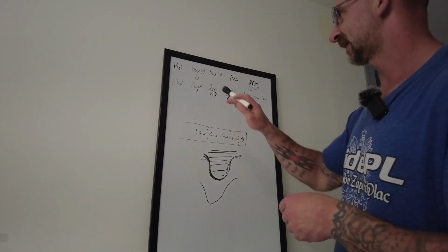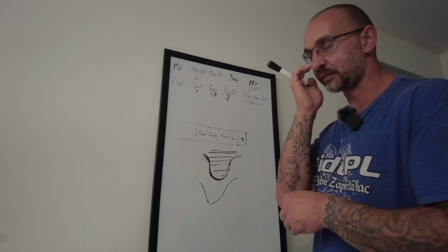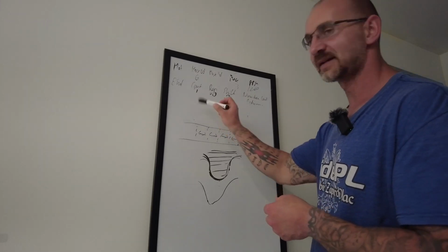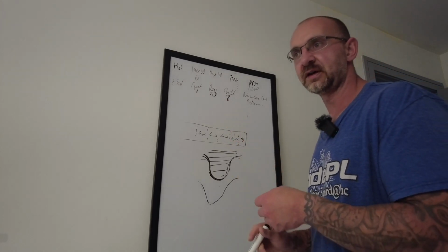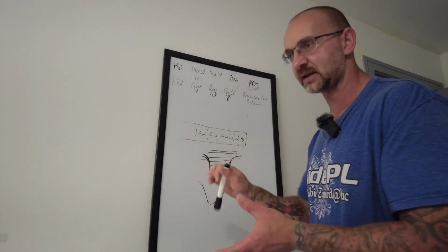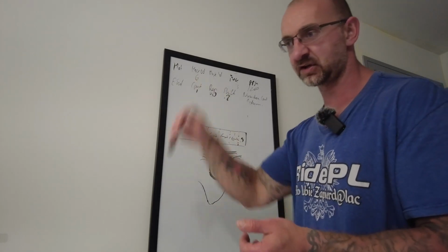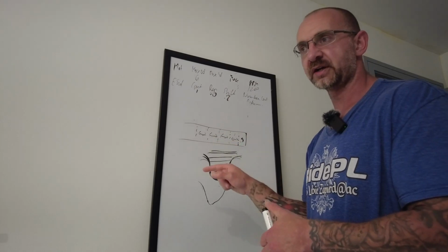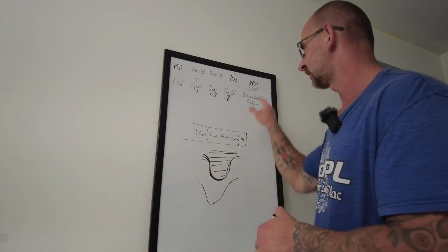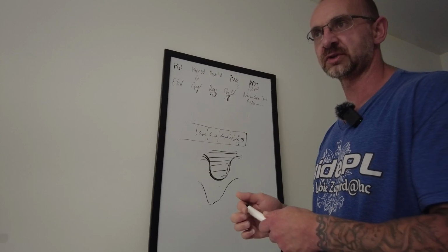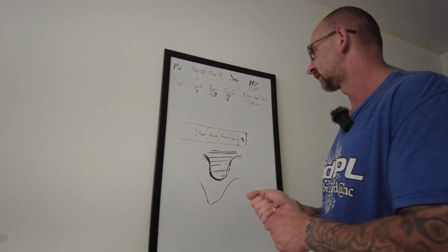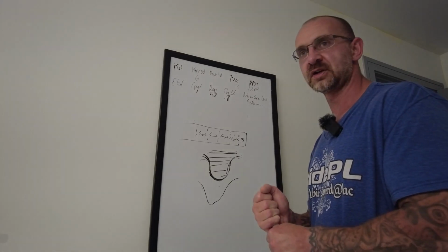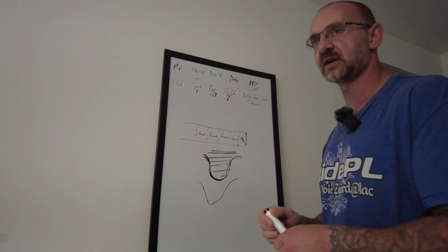Like I said, sometimes when you look at the program you made, you don't remember exactly why you programmed it that way, so just add a comment. If you use M2 for knocking off or breaking parts so your machine doesn't come and plunge into the part you already machined, make a note that when you run this part, press optional stop, so it's going to read that M1, if you don't want to use M0, for example. And yeah, so this is your header and end unit. Whatever you put in your body, these two things are very important.